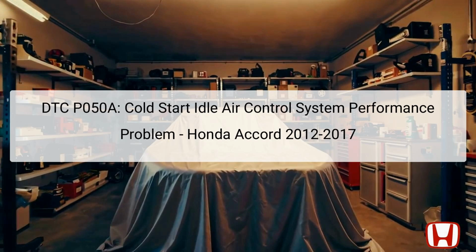The primary components affected include the powertrain control module, PCM, the intake air control system, and the ignition timing mechanism. Understanding how these components interact is crucial for diagnosing and rectifying the problem. The DTC triggers a warning under specific conditions, notably when the actual intake air volume falls below the target volume, signaling a malfunction. Effective diagnostics can help in rectifying the issue and ensuring optimal engine performance.